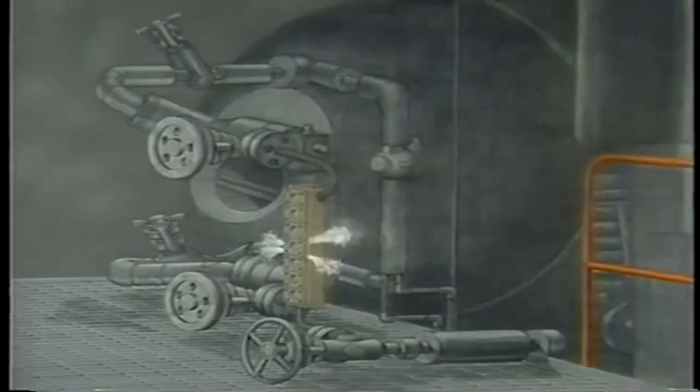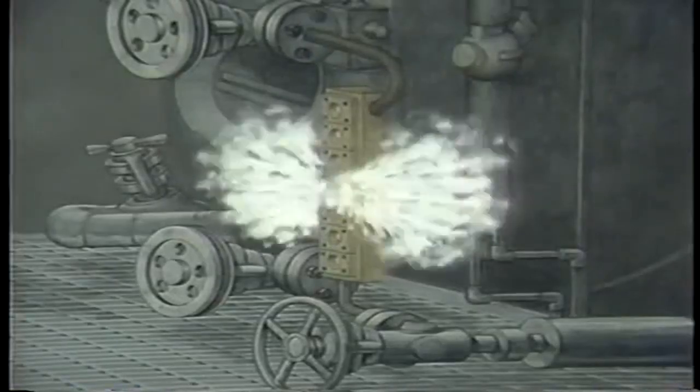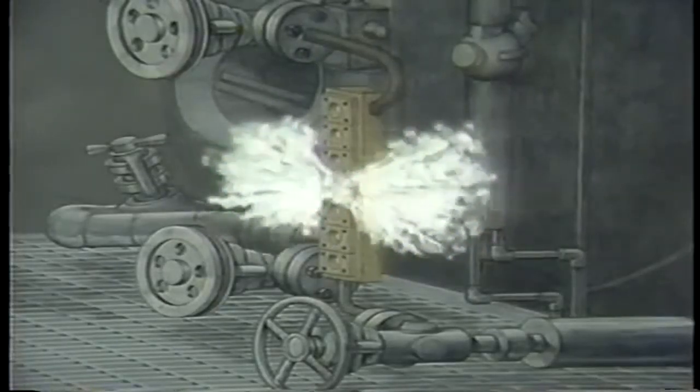or the operator may isolate the gauge glass by closing shutoff valves on either side of it. Once isolated, maintenance can be performed on the gauge glass while the boiler continues to operate. Once in a great while, a gauge glass may blow, spraying water and steam around the area of the boiler drum. This situation could endanger the safety of the people in the plant and the operator's ability to maintain proper